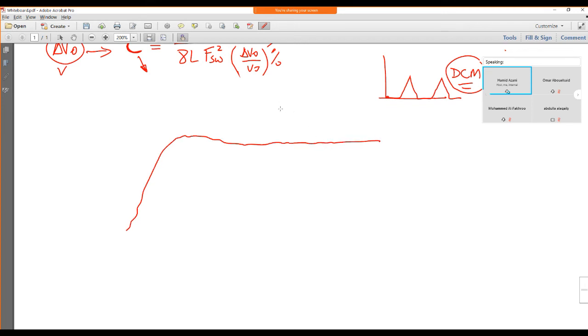So you judge your circuit in that stage, not here. That's why in the lab manual, we are asking you to plot the 5 switching frequencies. You go to steady state, and there you can zoom, you can just screenshot 5 switching frequencies and plot them for your report.